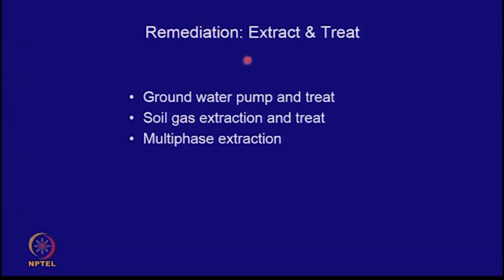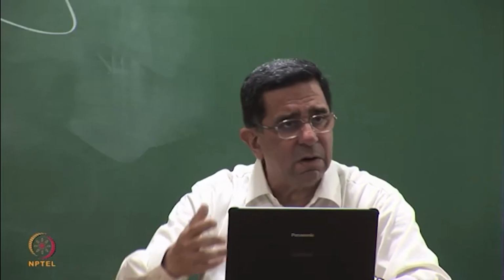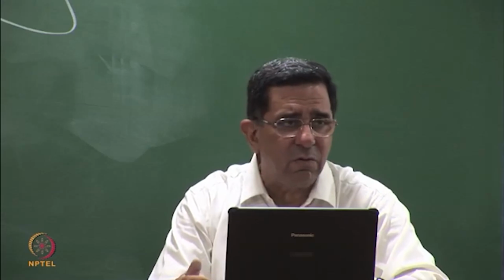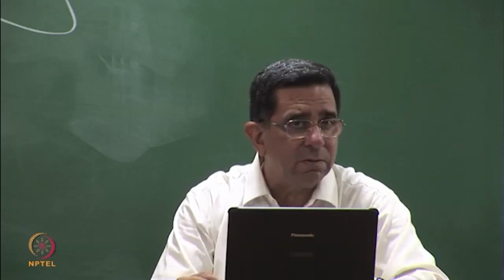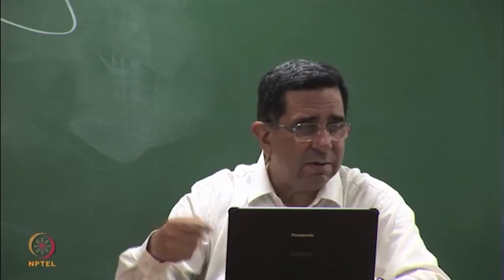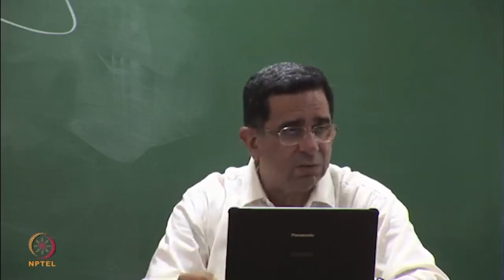Another remediation philosophy is extract and treat. You've got soil which is contaminated, you've got groundwater which is contaminated. The philosophy is very simple. I'll take out the groundwater because I can easily pump it out, and I'll treat it and inject it, or I'll take it out and treat it, inject fresh water.